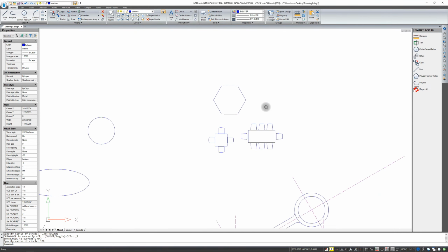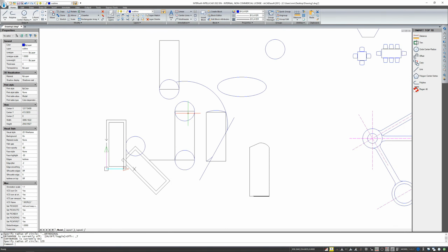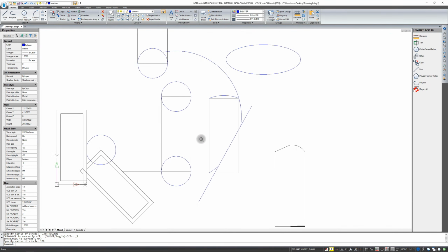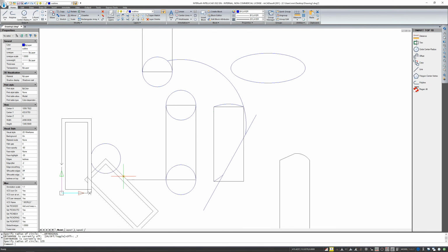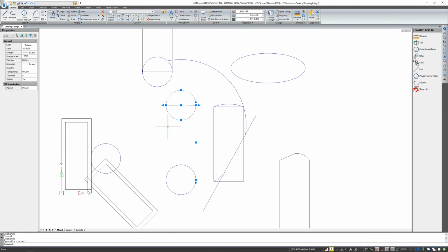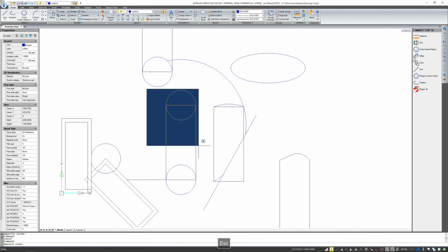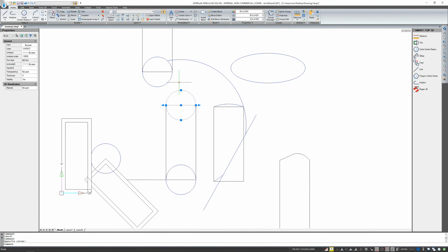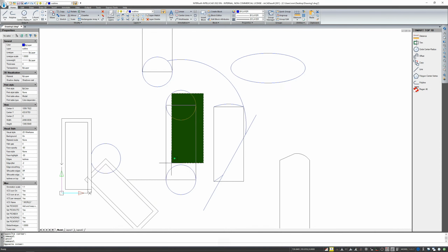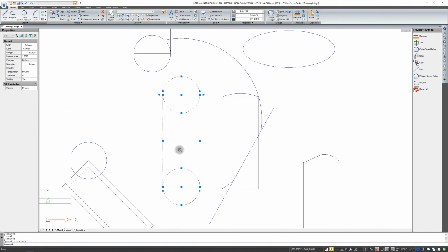And here on these elements, I would like to show the scaling option. If you are scaling something that consists of one element like a polyline, we only select that element. Here I have a lot of elements, a circle, and a lot of lines, so I select all of them. Please remember that from right to left selects everything, even what is selected with only a small piece of it. Everything that fits into your selection outline. And from left to right only selects what is entirely within the selected area. This is quite important, especially when there are already a lot of elements in the drawing.